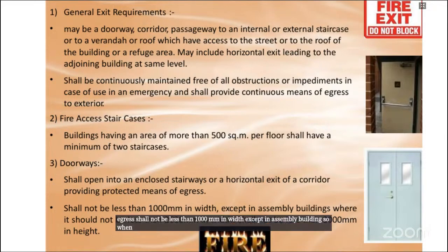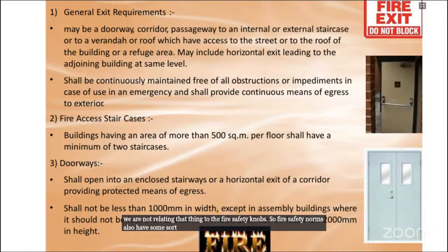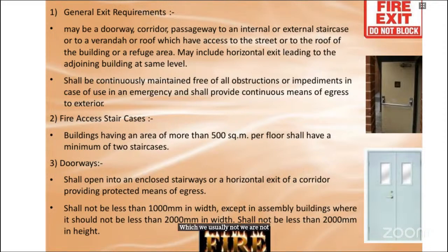When you talk about the width of doors, you are very much aware of anthropometry, right? You are very much aware of the width of a door in the context of ergonomics also. But we are not relating that to the fire safety norms. Fire safety norms also have some equal balances. As we say, it should not be less than 1000 mm, which we usually are not doing, except in assembly buildings where it should not be less than 2000 mm in width.